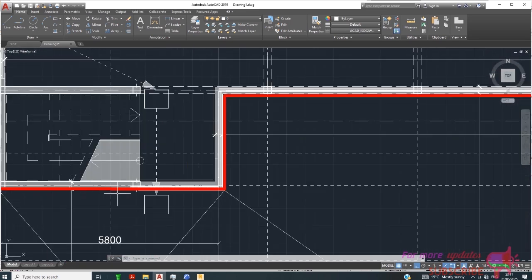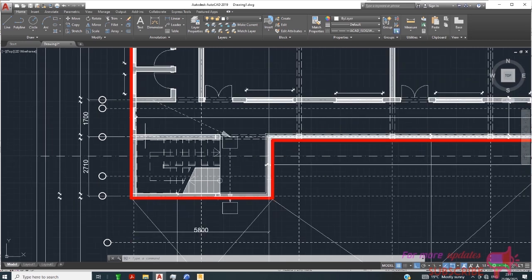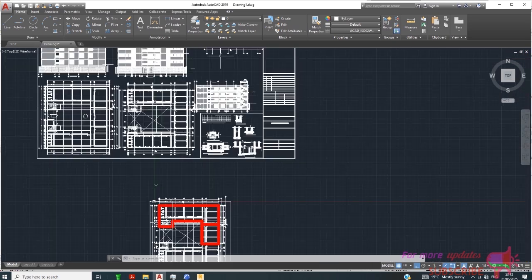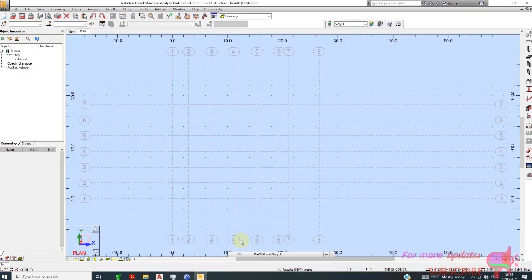And then for the staircase, it's usually good that my column should not protrude because this area is very limited. So I just use 400 by 200 because my wall is 200, and I don't need my columns protruding outside the walls. I don't want them to be visible in the staircase region. Also, I'm using 200 by 400 because this staircase has a water tank at the top, so it is carrying a lot of load from the water tank. So I will create my columns.